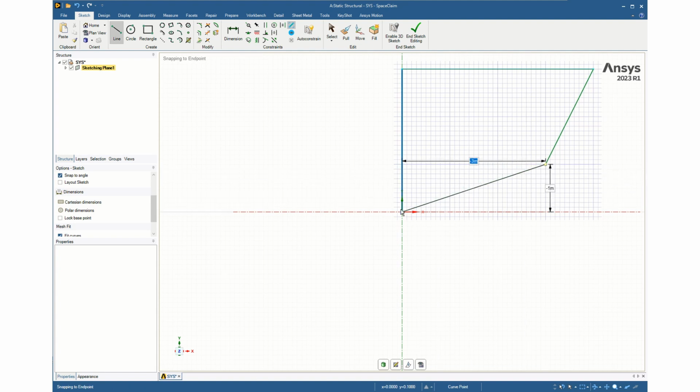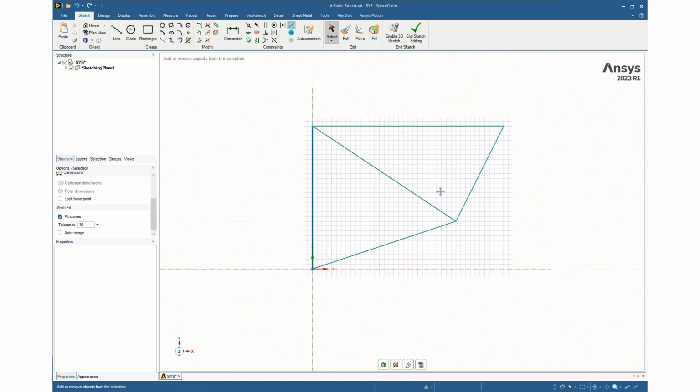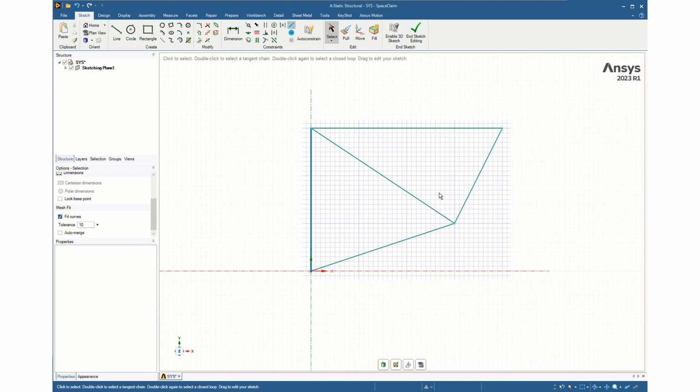Now I can click that point and come to my origin, and I have one more line to click. So I can come up here and click escape so that I don't create it from this point, and then I can click this point and bring it over to this point and let it go. And I have now created all the members of my truss. I can go ahead and hit escape, and that brings me to where I can draw a line. If I hit escape again, now I'm back to a neutral position. I can hit Control middle mouse button and drag my drawing to the center of my window.